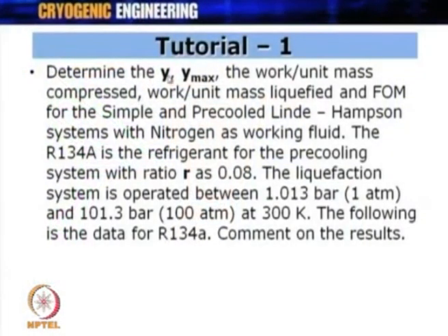Determine the yield Y, the maximum yield Y max, the work per unit mass of gas compressed, the work per unit mass liquefied, and the FOM, which is nothing but figure of merit, for the simple and pre-cooled Linde-Hampson systems with nitrogen as working fluid. Now, it is very important to understand what is asked in the problem. So, what is your working fluid? It is nitrogen. What are we talking about? We want to talk about both the cycles, that is the simple Linde-Hampson cycle as well as the pre-cooled Linde-Hampson cycle.